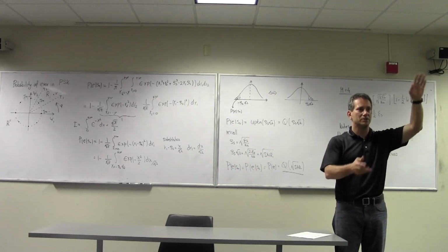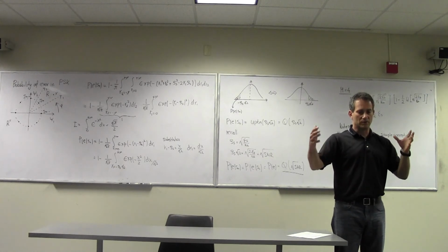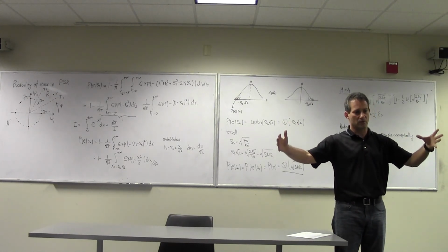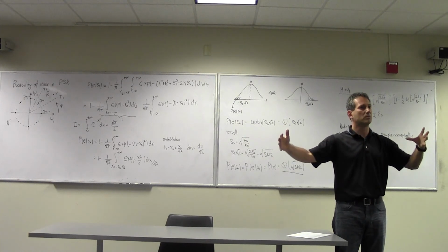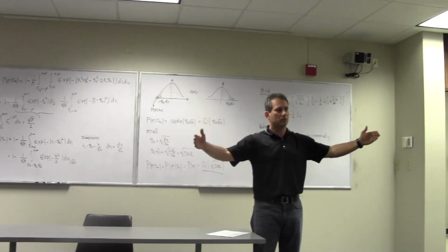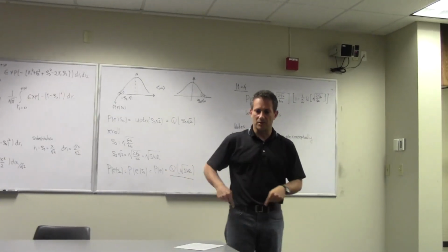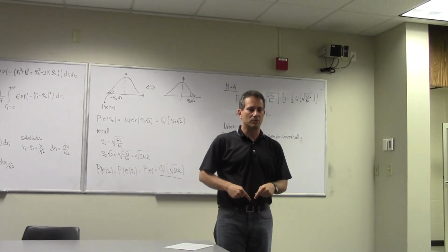You have I and Q branches and you modulate them with the proper magnitudes. So when you dimension a system for coverage, for the range, you base it on the lowest modulation that you're going to use. You're going to say, if this system works with BPSK, you can go 3 miles. And that means I'm going to cover a 3-mile radius and have the ability to communicate.